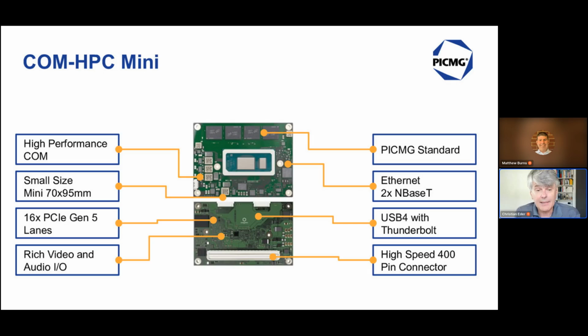The latest size which was introduced was the Mini. It's much smaller. It only features one connector, 400 pins, let's say half the amount of the client, but still has a lot of features here, like 16 PCI Express Gen 6 lanes and 2 Ethernets, USB 4, of course, everything which is state of the art.